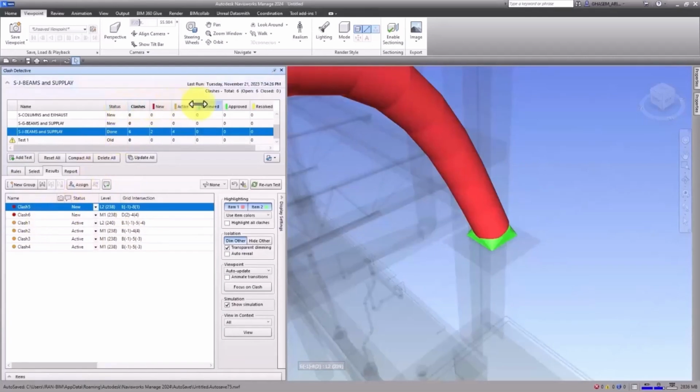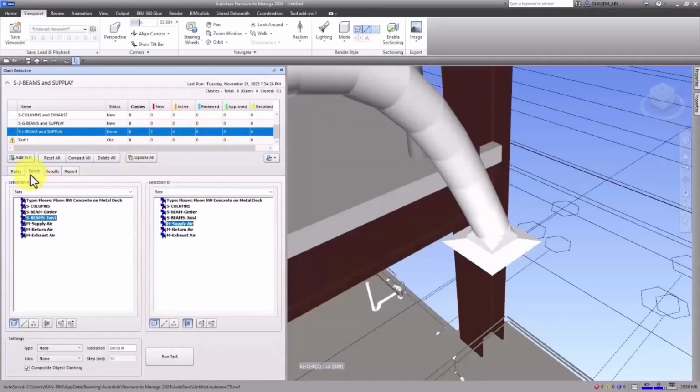Okay, look at here. Here in status, first of all, here you can see the last clashes. And when you take a glance on this, you will see that here we have 6 clashes. And 2 of them just added to this list. Because if you remember, we did it once, there were 4. And I wanted to have self-intersect, and 2 new clashes are added here. 2 of them are seen for the first time, and the others are active. These are the information of this section.